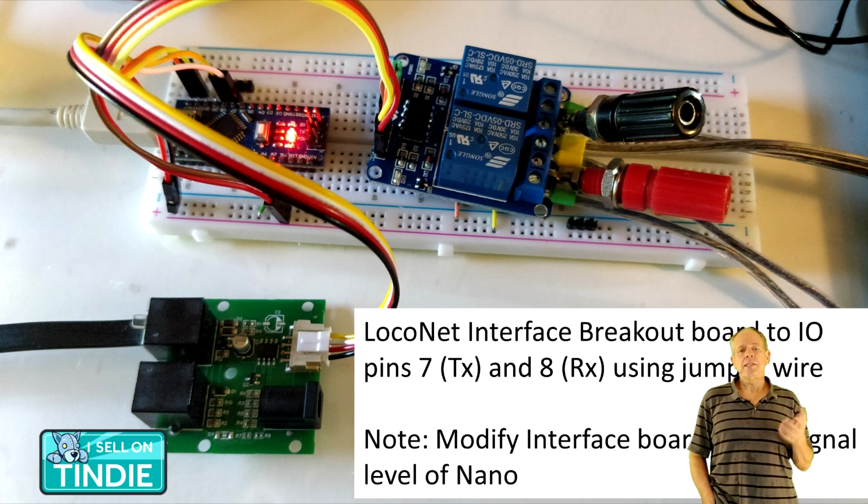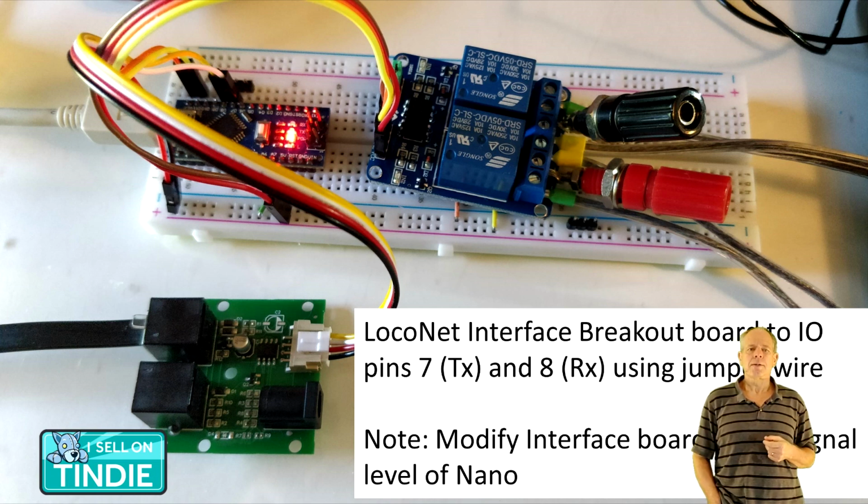Note that the receive pin must go to pin number 8, as the LocoNet library makes use of a special interrupt input of the Arduino, which is only available on I/O pin 8. The transmit pin can be chosen as you wish. However, I usually use just the next input, as I like to keep related things together.